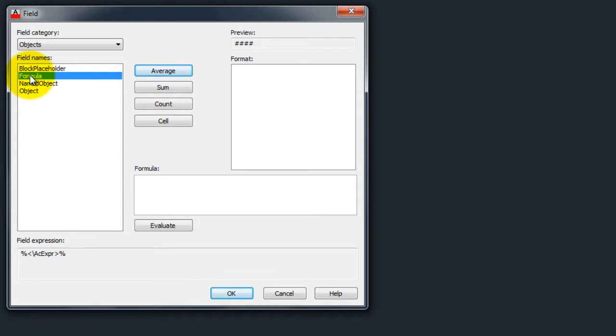Well, as you can see, I will use formulas to display the values in AutoCAD. This is definitely something you don't have to do, but I highly recommend to use formulas because, in my opinion, they offer really great flexibility regarding the display of the values in AutoCAD. I also know offices, for example, that draw in centimeters or in millimeters, and in this case you will definitely have to use a formula to correctly convert the values. So you have to use a factor to translate square millimeters or square centimeters to square meters.